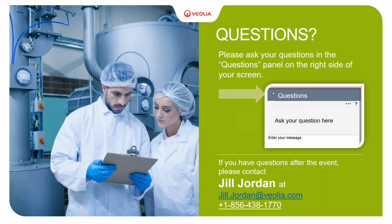Similar to the question we talked about municipal anaerobic sludge, if they have a high rate system, a UASB or EGSB, would you still avoid using that for seed? Oh yeah. I wouldn't use municipal flock sludge to seed an EGSB or UASB reactor at all. In fact, it won't stay in because it doesn't have the high settling velocity that the granular sludge has.